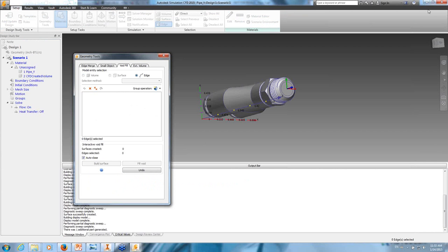So there are 2 workflows. If you bring in a cavity into CFD, it will automatically generate that extra volume for you. So I'm just trying to save you some clicks. Yeah, if that cavity is watertight. Right. Yeah, and that's why you would add those caps to make it watertight, and then this volume that I just generated would be automatically generated, and you won't have to do that. Right. And sometimes you don't maybe even have that edge. If you have some kind of spherical surface or rounded surface, you might not be able to grab an edge. And of course, then you can suppress those caps and get them out of the design.